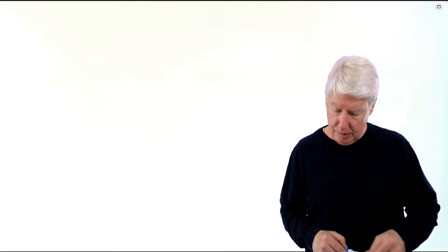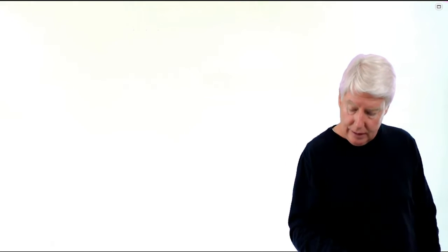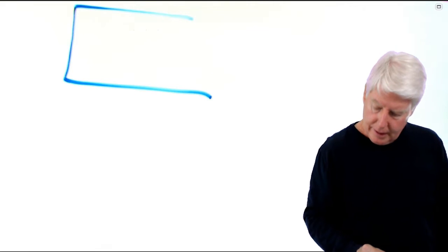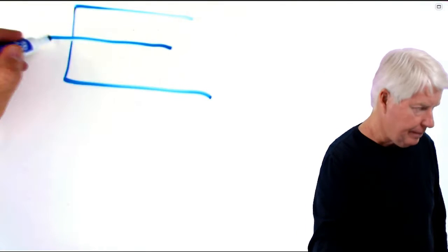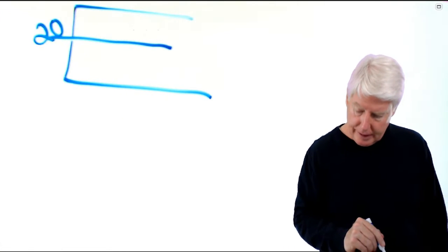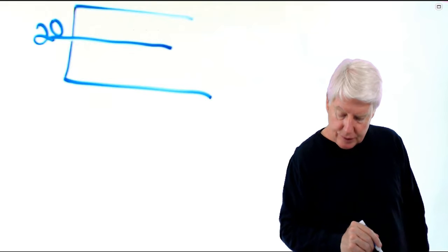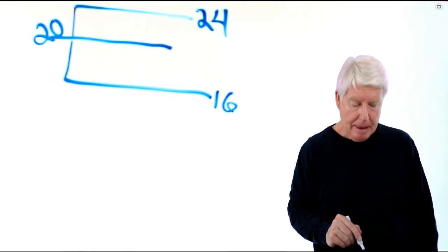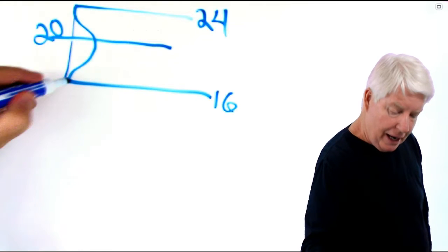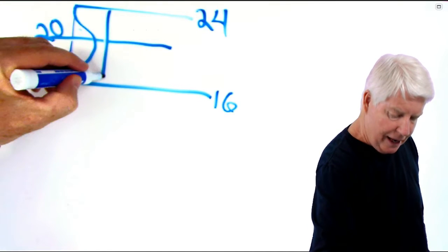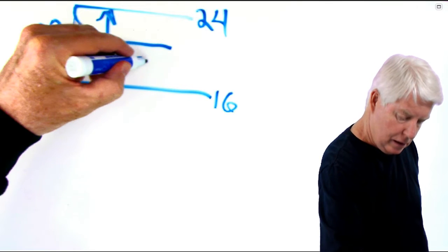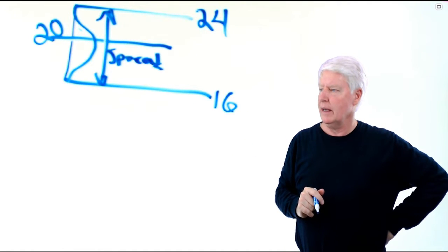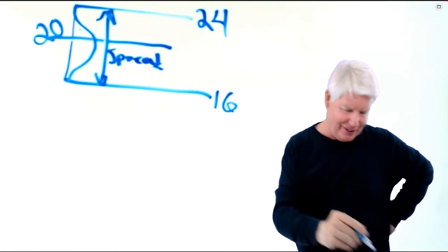And this is number 4. So what we have is an SPC chart, and the average is 20. And upper and lower control limits of 16 for the lower control limit, 24 for the upper control limit. When they say the spread, they mean plus minus 3 sigma. The spread is that plus minus 3 sigma, and we know the control limits are plus minus 3 sigmas away.